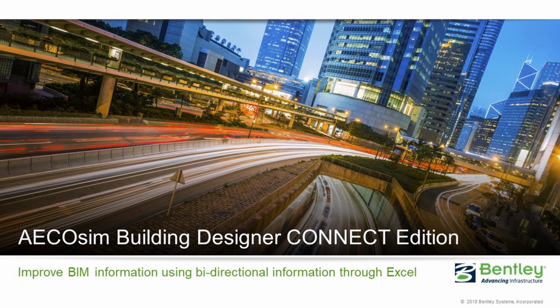In this session, we will see how we can enrich and update our BIM project with information using the AECOsim Building Designer and Excel bidirectional link. We will see for which type of information it is very beneficial to use this feature. Using this process, we can benefit from the Excel interface to quickly define and add some data to our BIM project. We will see why this tool is key to maintain the data up to date all through the design process.